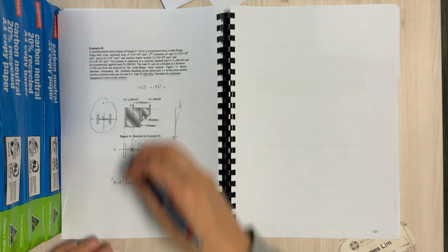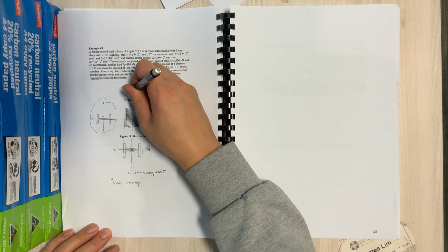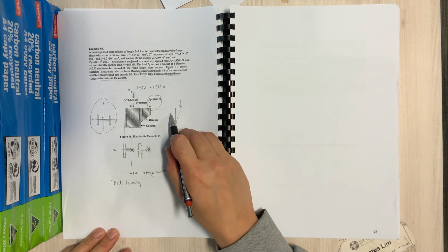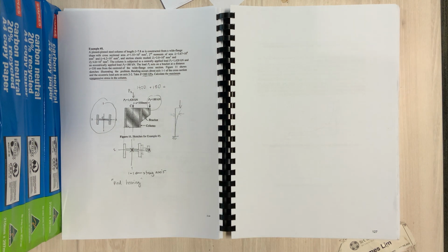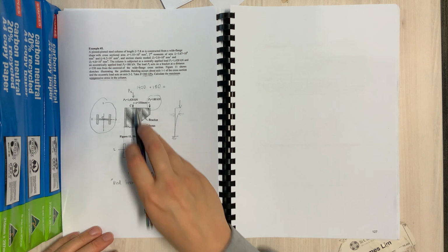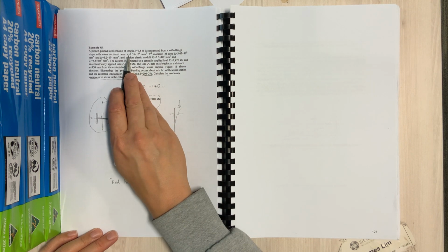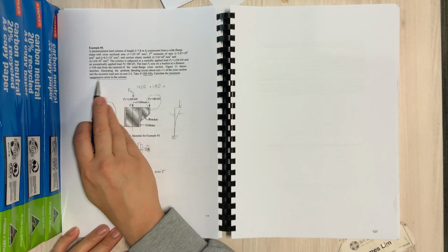That's almost like saying let's move the P2 load so it's also through the centroid, and then ignoring any buckling or any additional deflections, for example, we would be able to work out the axial component of the stress. So perhaps just as a starter, 1420 plus 180 will give you a total force, and divide that by the cross-sectional area, 1.55, and that will give you the stress.